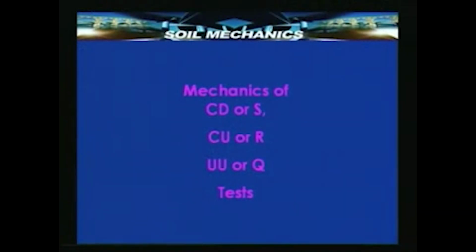Now, let us see the mechanics of these tests, and unless we understand the mechanism involved in this test, how the stresses are changing, we will never be able to understand what is the kind of shear strength parameters which we are getting from these tests. Are we getting total stress parameters? Are we getting effective strength parameters? If we are getting the total strength parameters, how to get the effective strength parameters from them, and so on.